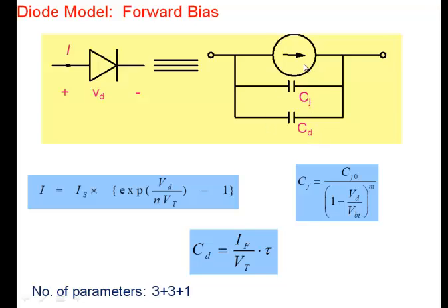You can calculate all of that. So every model will have a set of parameters here. So all my PN junctions will have this particular model, this mathematical structure. What will differ from one diode to the other are these parameters. Now, a more complicated model will have more complicated mathematical equations, more parameters, and the model will become more complex. It's not that this is the only model that I have. Okay.